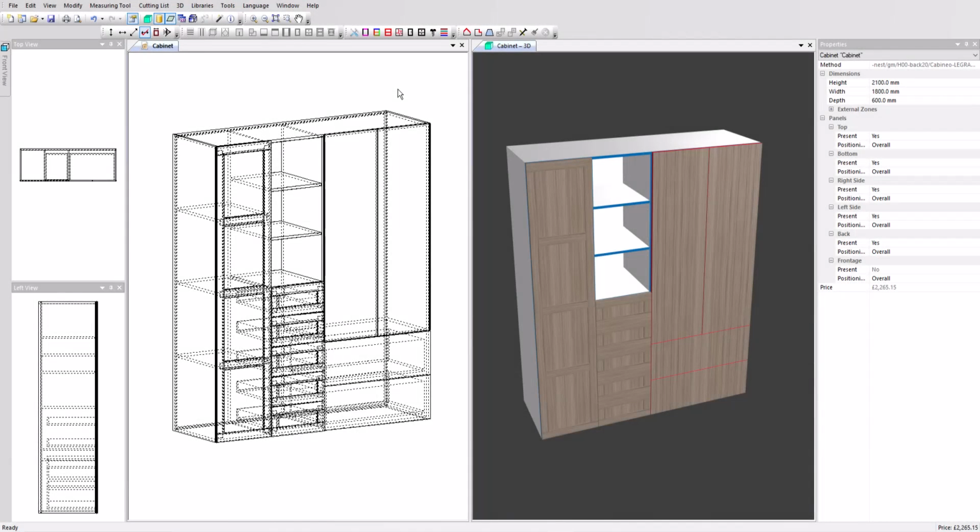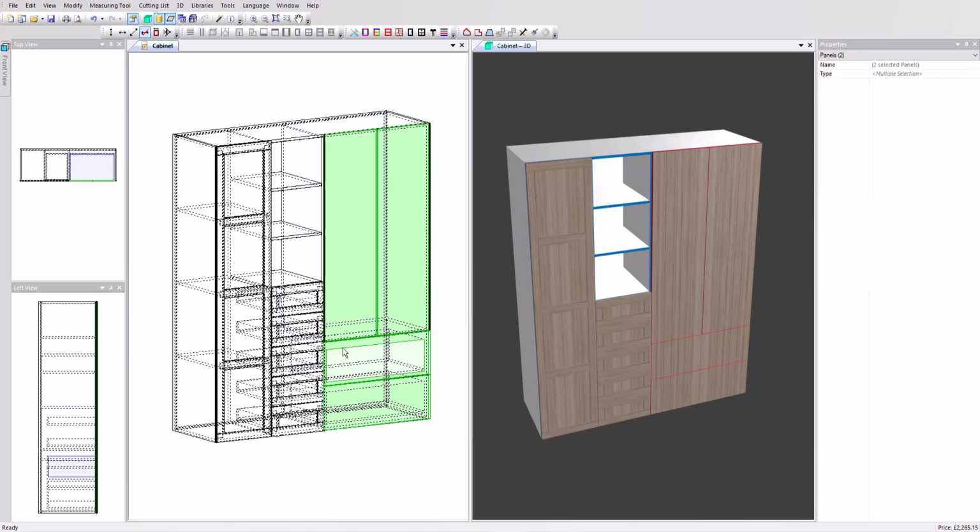This test cabinet in PolyBoard includes a frame and panel assembly on the left, so we can show both the bar and panel optimizations. On the right we have frameless facades to show you OptiCut's perfect grain feature. This ensures the parts are placed next to each other on the panel, so the grain flows naturally across them in your finished project. With all these facades selected, we can right-click to see that we've already activated the grain continuity feature. Now we'll go to the cutting list menu and select OptiCut Export.